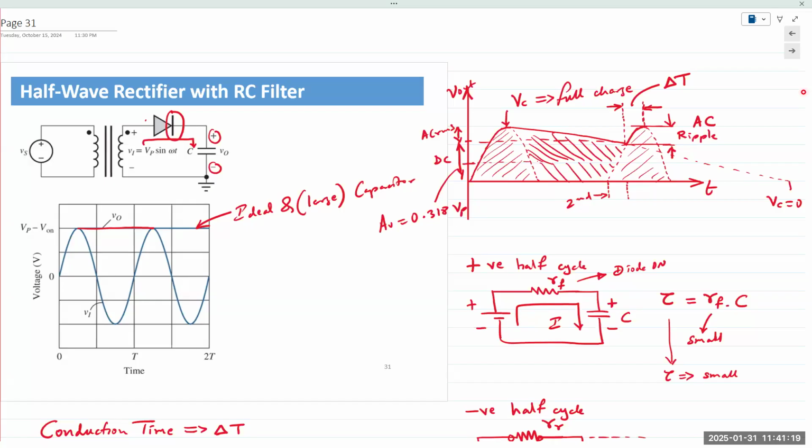Yes. Ideal diode, it would not discharge at all. It would be a flat line, really flat line. And this is just, of course, just a capacitor. In real life, of course, you'd have a load resistor and you'd connect a capacitor in parallel with that load. But the point still remains. Tristan, you had a question? Okay. Does everybody understand the fundamental operation of the capacitor?